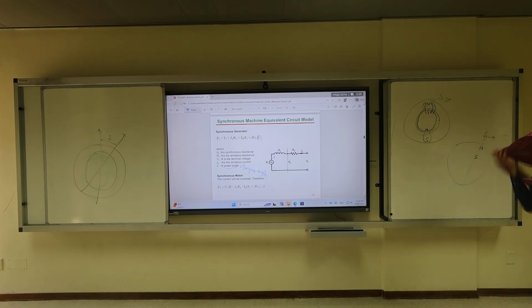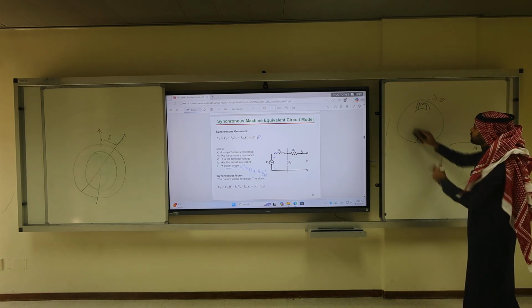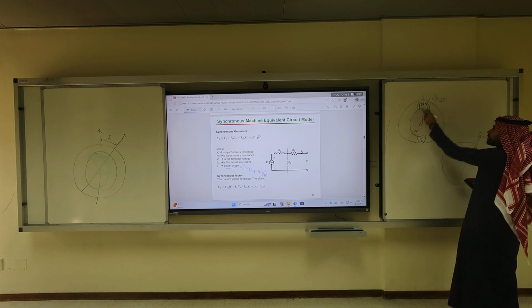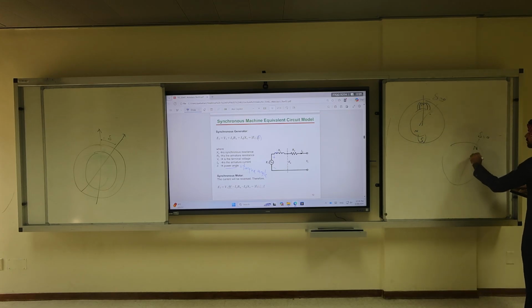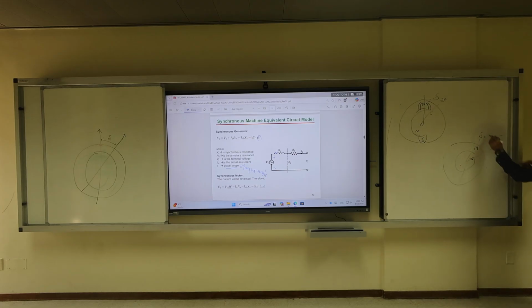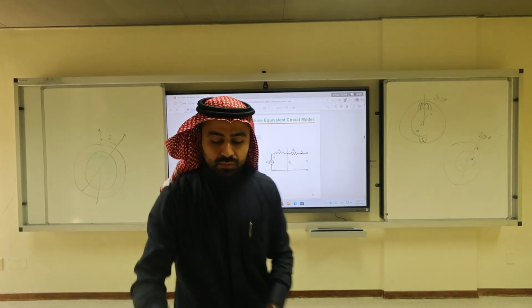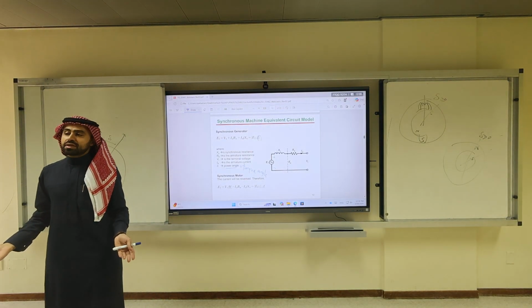Yes, it is a synchronous machine, but what I'm telling you is if you already have a certain delta from the beginning, the south is here and the north is here. Already you have a deviation of the axis. So they rotate over time. This delta is greater than 0. Because everything is AC, the poles are rotating over time. So it should be a constant value. Yes, it has to be constant. Otherwise, your output will not be uniform in the synchronous generator.